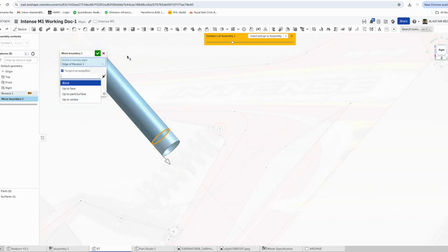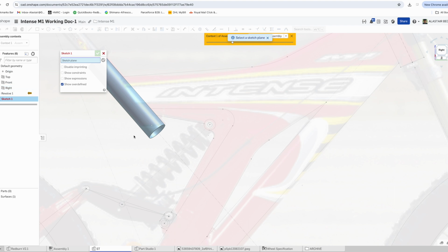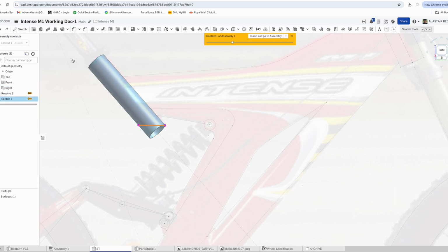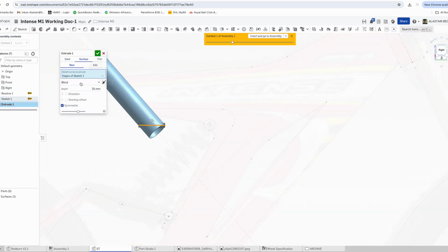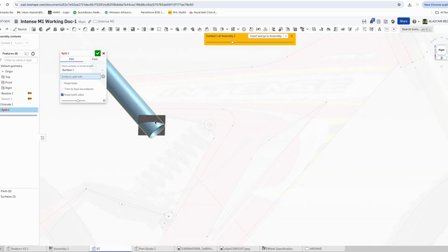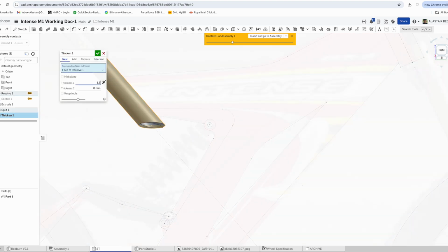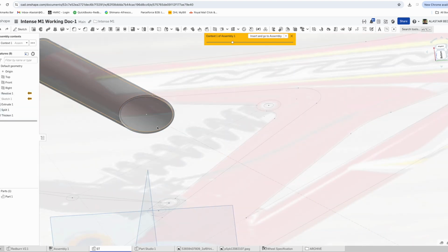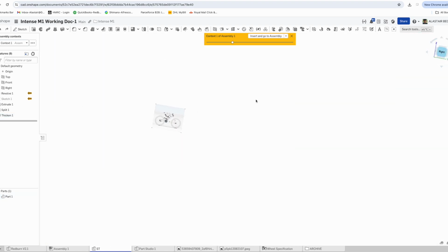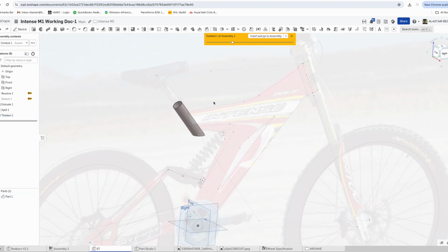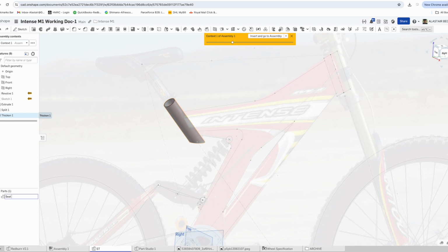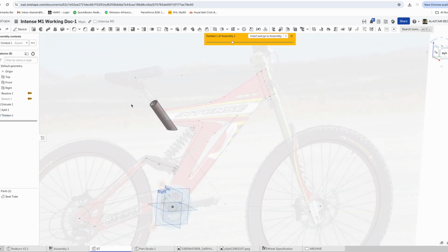So yeah, we're just adding this seat tube in. I think modeling this as a surface, and then we'll thicken that to the right thickness. So it's probably a 30.9 seat post, from what I would imagine a downhill bike was back in those days. So we're just going to give it a wall thickness, check the internal measurements, make sure that's all right. And there's a seat tube, so we'll name the part, and then we'll essentially start to bring that part into our sub-assembly.